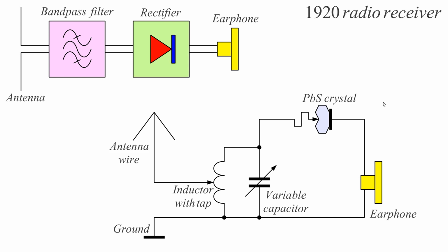Unfortunately, the lead sulfide crystal was very good at this work, but it was also tricky to work with. It could be easily damaged with over voltages, say from lightning collected by the antenna. It could be easily damaged mechanically. It's not mechanically very stable, so it was not a very good diode, but it had some interesting properties, so it could work with very, very low voltages, both on the RF side and then the audio frequency side, getting to the earphone.